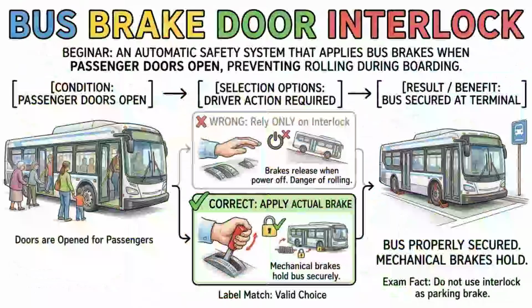Transporting hanging meat in a refrigerated truck is another highly specialized scenario frequently featured on the commercial driving exam. Carcasses suspended from the ceiling of the trailer have a very high center of gravity and will swing back and forth like a pendulum when you steer or brake. This swinging motion creates a delayed push on the vehicle, meaning the momentum of the meat will hit you a second after you have actually made your maneuver. To prevent a rollover, you must drive extremely smoothly, braking and steering with maximum gentle care.